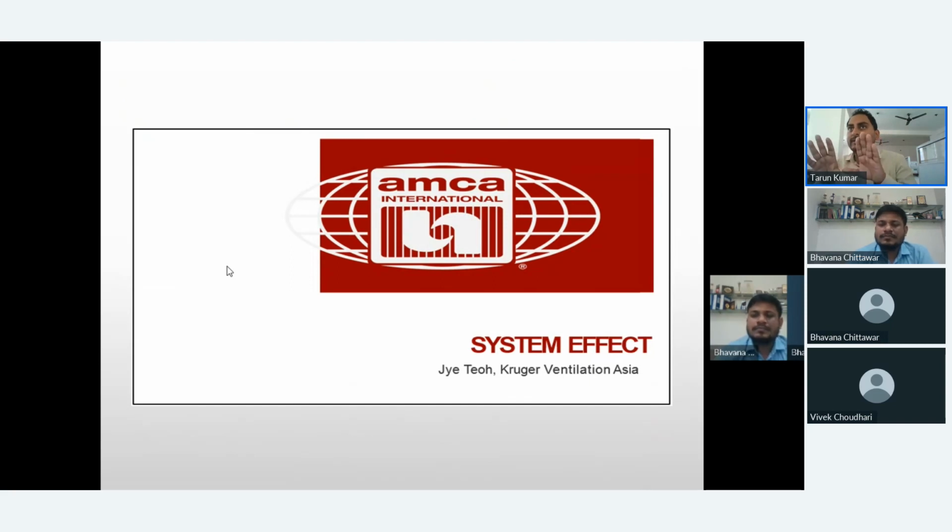EC fans are nowadays coming for retrofit jobs also. Whenever a DIDW fan is installed, they will remove the DIDW fan and put in EC fans in a multiple series. In that case also the system effect comes into the picture. As per AMCA guideline, there should always be a minimum gap of 2 times the fan diameter available in the system.